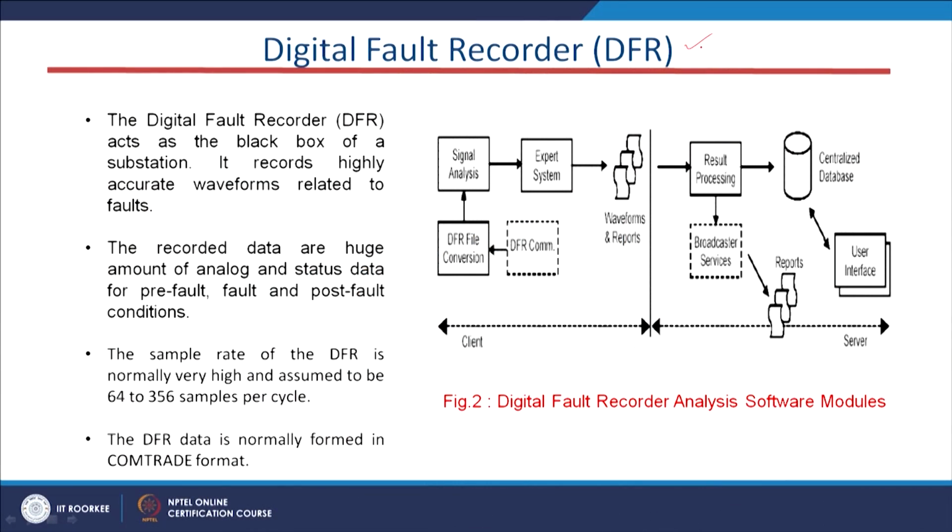This is the digital fault recorder, known as DFR. This is the basic block diagram for it. We acquire the signal, and we have an expert system, and from the expert system we can store the data or process the data for further actions. This digital fault recorder acts as a black box of a substation, and it records highly accurate waveforms related to the faults.